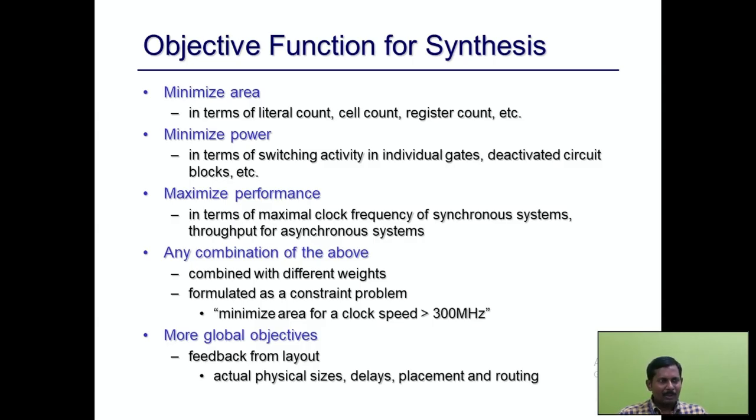Next, obviously we need to minimize the power. The power minimization depends on various parameters. It depends on the number of logic gates, on supply voltage, and on switching activity. Here we majorly focus on the switching activities of individual gates.